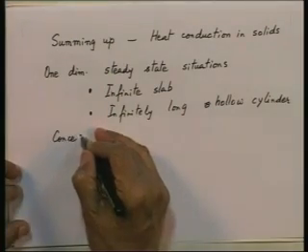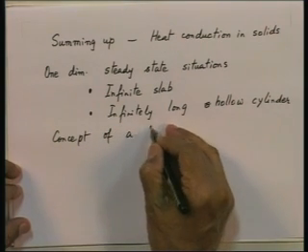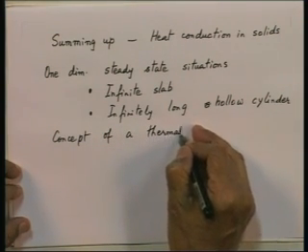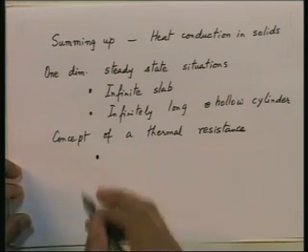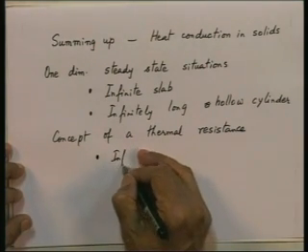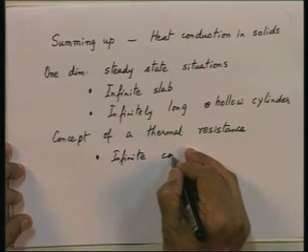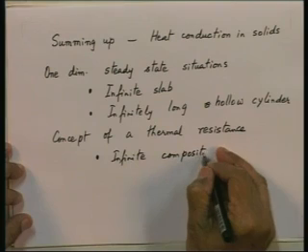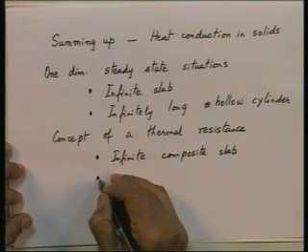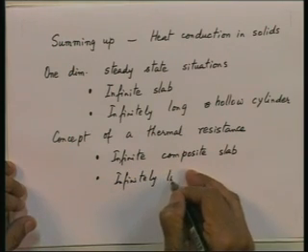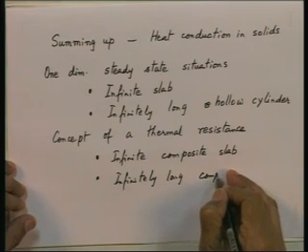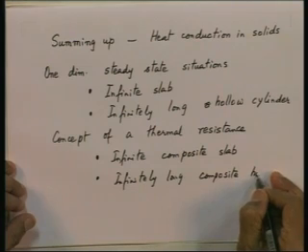I told you how to solve on your own the problem for a hollow sphere. Then we introduced the concept of a thermal resistance, and we got expressions for the thermal resistance again of an infinite composite slab and an infinitely long composite hollow cylinder.